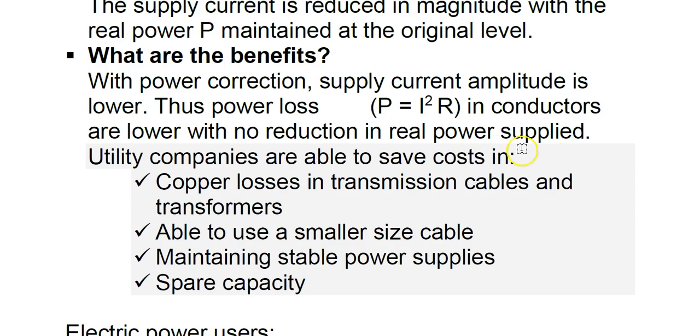So remember, we have this formula: power is I squared R. As long as we use cables with copper conductors, which also have resistance, there will always be energy used up along the way from the power station to where we want to use the electricity.